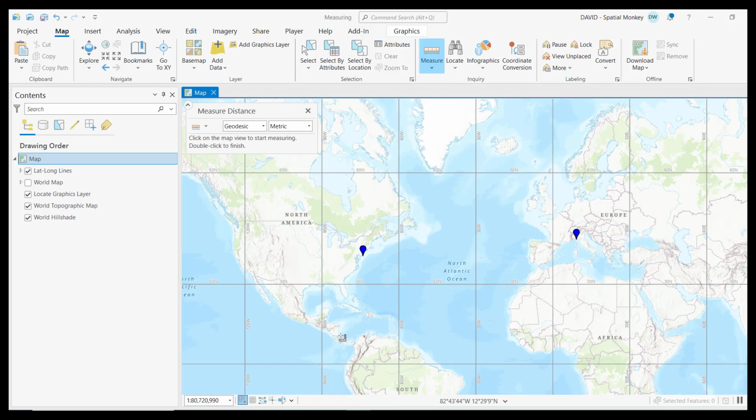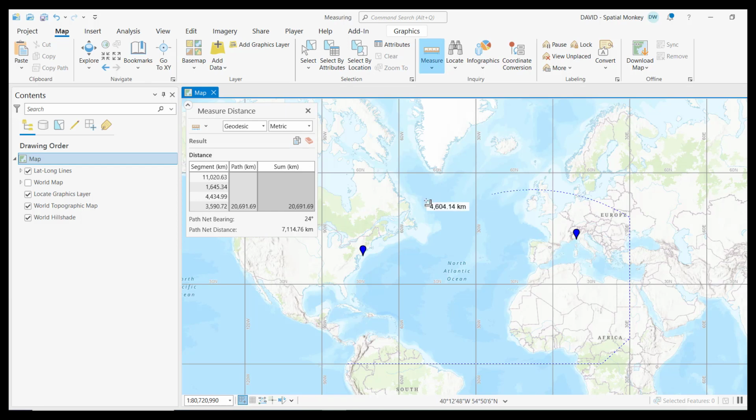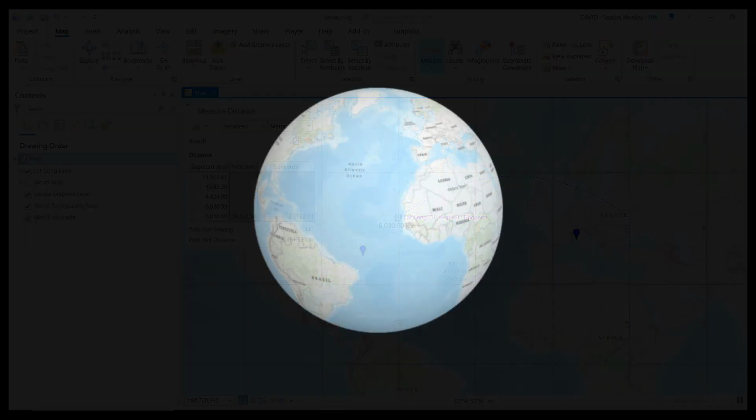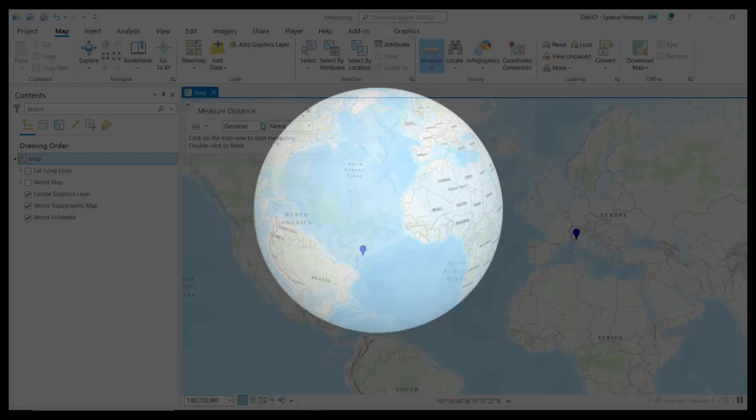This explains why when we measure along the equator and the lines of longitude using the geodesic option, the tool follows those lines. These lines are great circles, and therefore any points along these lines are the shortest path. When we move away from those lines, we can see the shortest path is curved in this particular projection. Technically, a great circle is the shortest path on a sphere, and the Earth is a spheroid. That is, it is slightly fatter around its middle, but it's very close to being a sphere, so great circles are often used to calculate the shortest distance on the Earth.